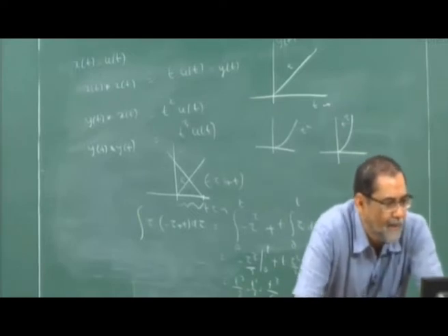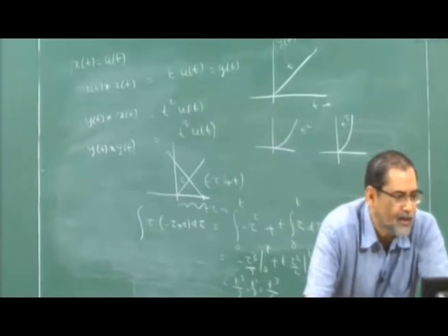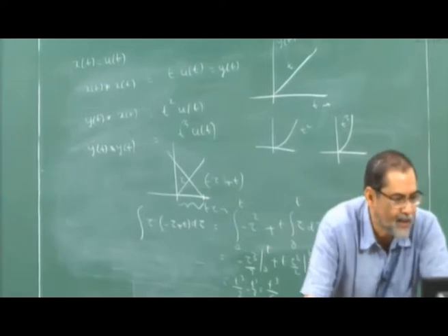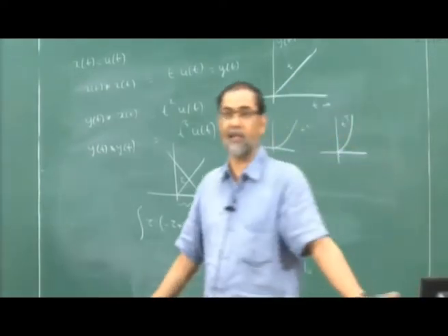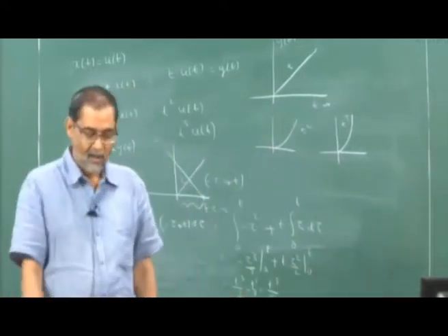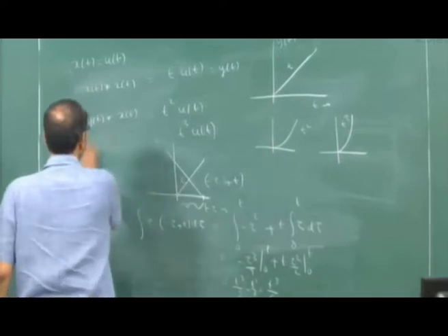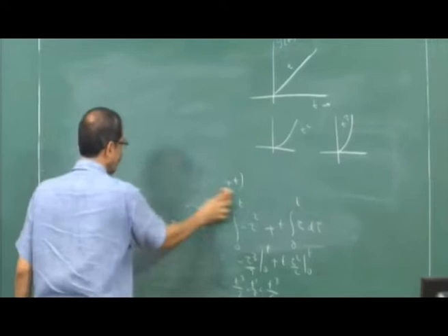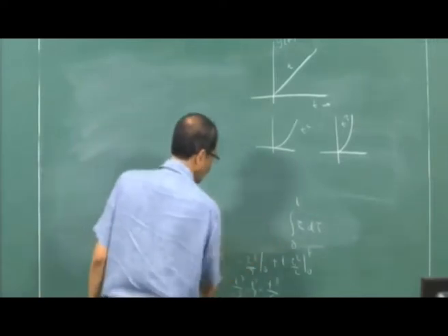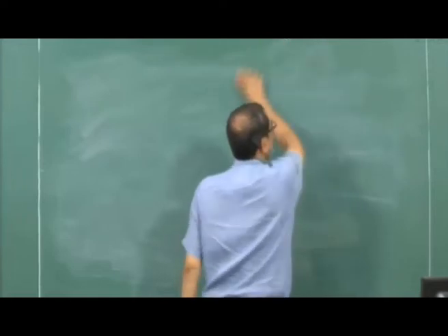Another question from PhD Tech: if H1(t) is a low pass filter and H2 is a high pass filter, and they are in tandem connection, can their connection be interchanged? I mean why not, if it's an LTI system? As long as both are LTI systems, it doesn't matter at all. We could do one first and the other next. So a tandem connection doesn't put any condition.